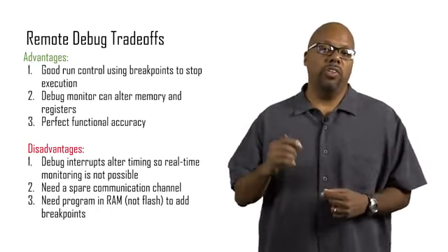Okay, so another way to go, which has become more common in modern processors, is the use of an embedded debug interface. You see this in modern processors nowadays: embedded debug logic that's actually built into the processor. Inside the processor or the microcontroller, in addition to all the logic that actually executes the code, they put debug logic, hardware that actually does debug activities. They build it right in.